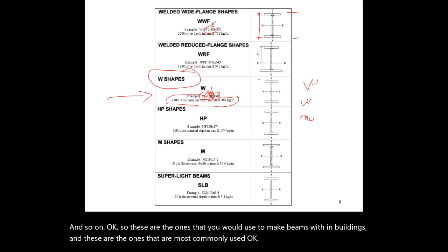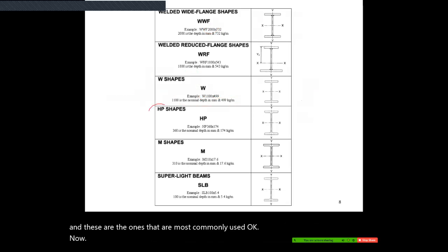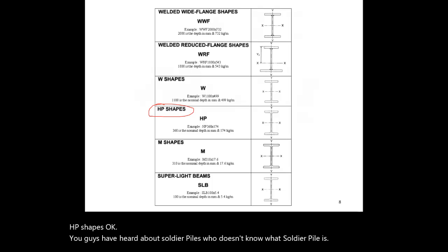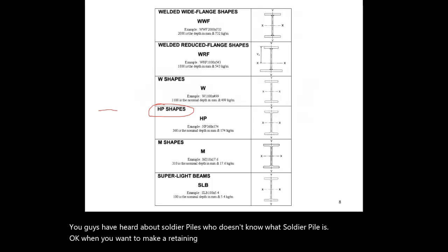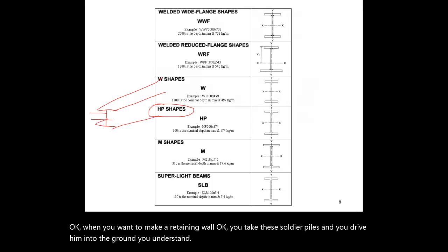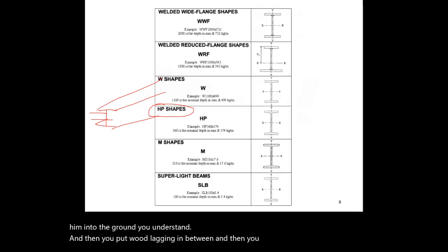Now, HP shapes. You guys have heard about soldier piles? Who doesn't know what a soldier pile is? When you want to make a retaining wall, you take these soldier piles and drive them into the ground, you understand? And then you put wood lagging in between, and then you can start excavating the earth, and that acts as a retaining wall.